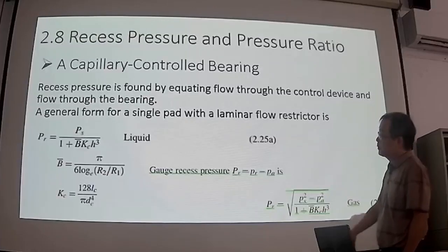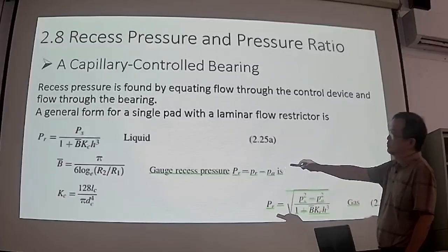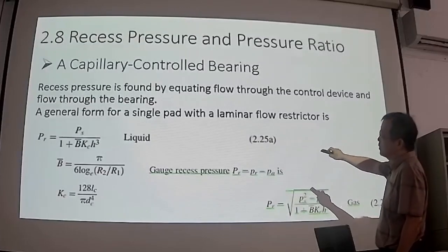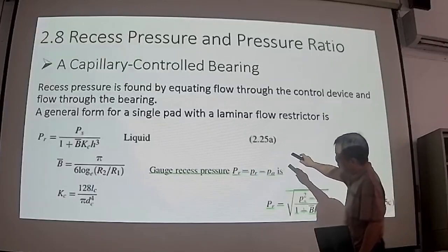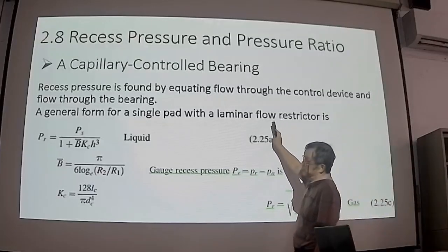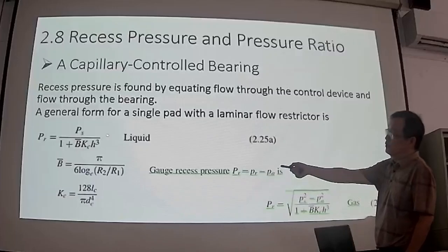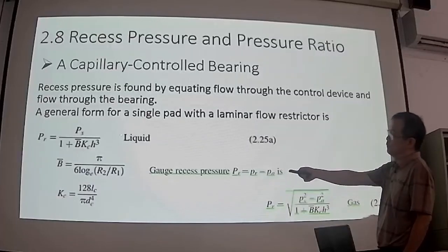So this kind of formula is related to different flow restrictors. In this case, for the laminar flow restrictor like the capillary, you can obtain this form of the formula for the hydrostatic bearing.